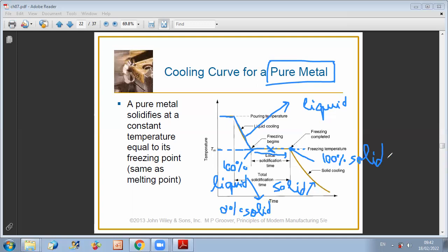But it's true that you have a constant temperature, but your material is losing heat. It's losing heat, but we say that this heat is not in sensible form. Sensible form means that you have it with a change in temperature. While when we say latent heat, this released heat is due to, if you want, a change in phase.